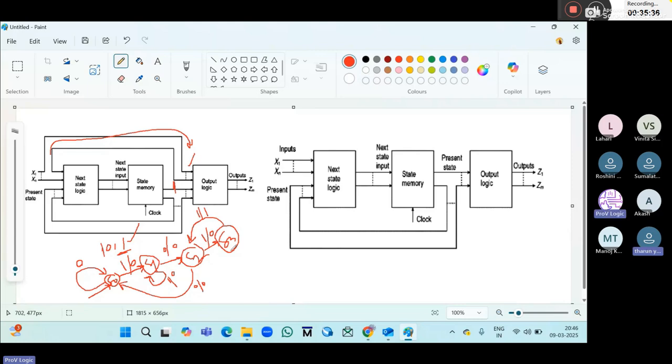I think S3 has to go to S0, right? Actually, to repeat the sequence 1011 1011, we need to send the S3 1 bit to S0. Starting from the initial S0. Okay, but here S0 will store only 0, right? Only 0 is passed, but this is overlapping, which means we need to count overlapping 1011. We have both cases, overlapping and non-overlapping.